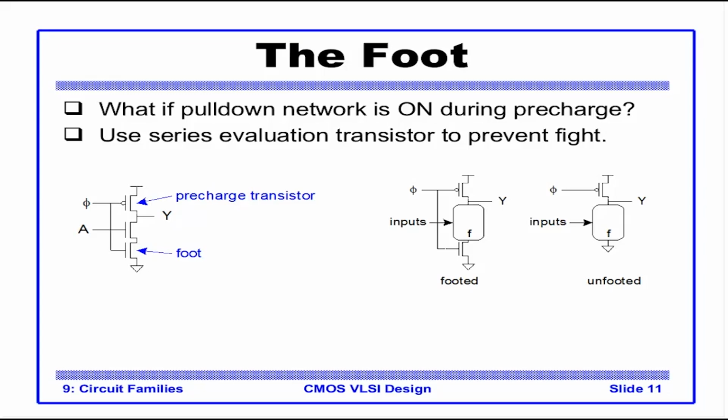So what we do is we add a foot. We add a foot to A, which is again driven by a clock. So whenever we are in pre-charge mode, this NMOS is off. So it prevents Y from getting driven by VDD and ground at the same time.